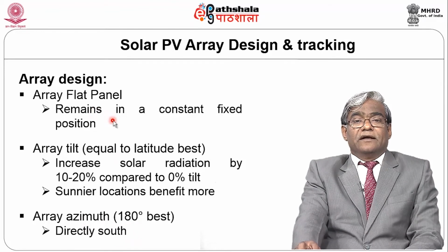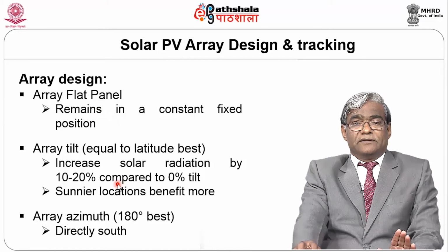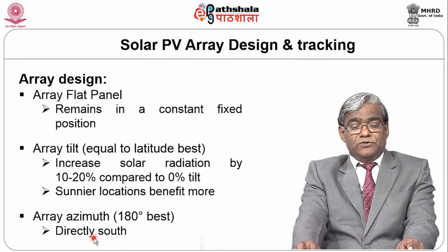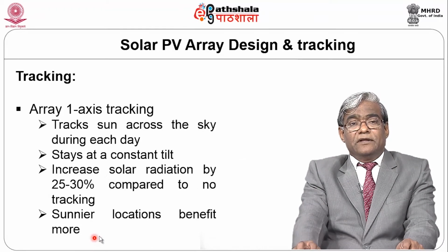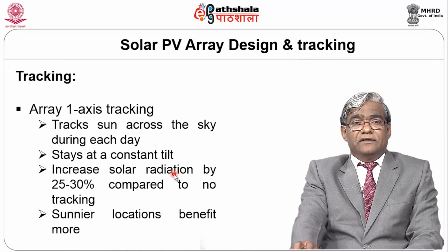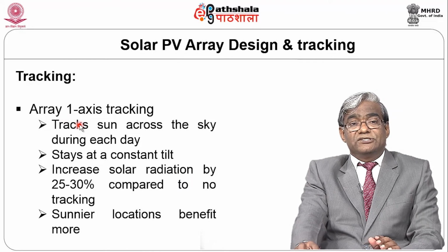And here the solar PV is fixed, and if we maintain the tilt equal to the latitude angle, then 10 to 20% improvement is there in the performance. And also it should face directly south, so that the performance could be further improved. And apart from the fixed type solar PV power plant, we can also have a tracking system.